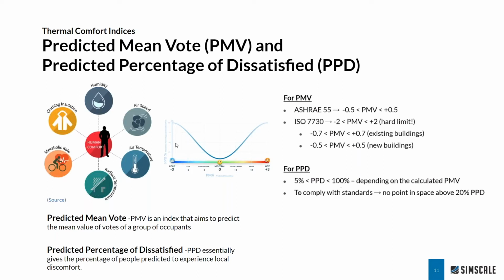So the next image you can see is a ratio between the PMV and the PPD. What you see on the screen in the legend is a 7-point scale specific to thermal comfort, starting from -3, which means the colder part, and it ends at +3, which is the hottest range that we can actually allow for a thermal comfort study. So how are these parameters actually defined, or how are they devised?